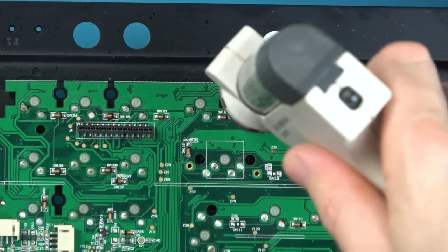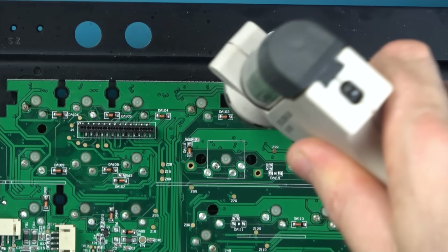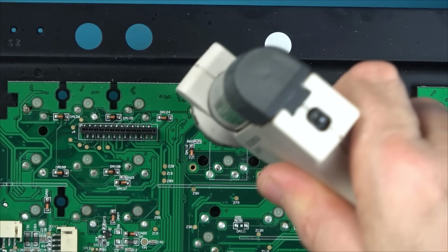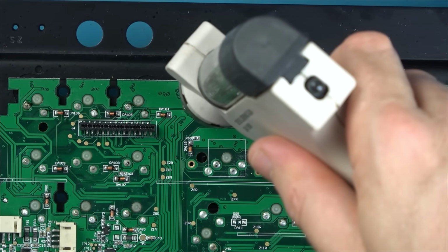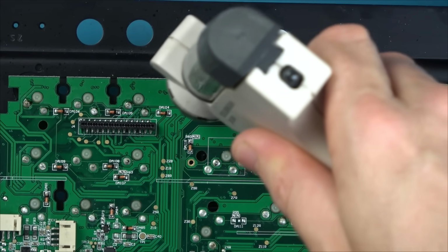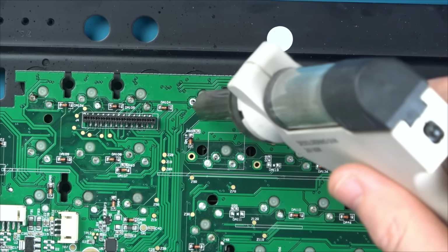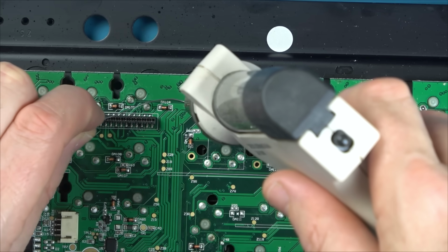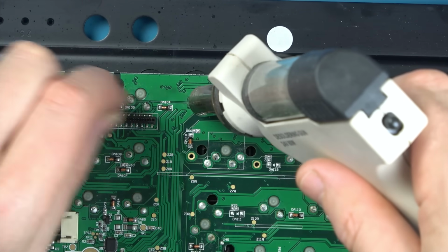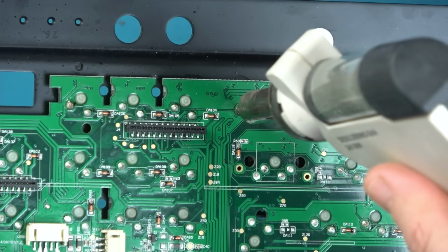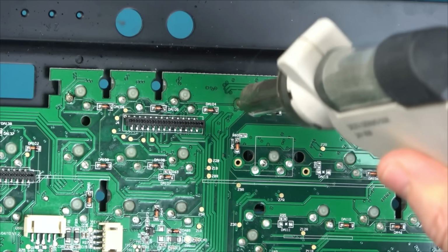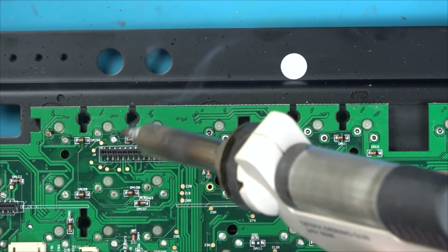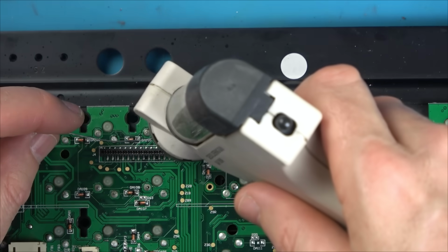It's weird I have to keep filming, because when I wasn't filming, every other one was getting blocked up. Now they're all cleared out. Oh, come on. Okay, well that's not quite clear. So all I'm doing is, look, put it on here and then just add a little bit of leaded solder while this is on here. And it saves me having to get a separate iron to do that, because that's still working its way into the hole. And that way it will clear itself out, because the leaded will mix with the unleaded and make it easier to come out.